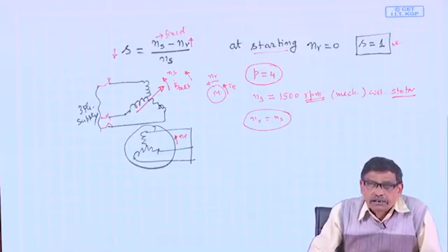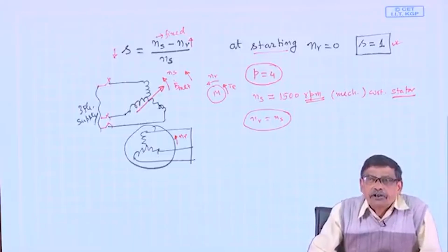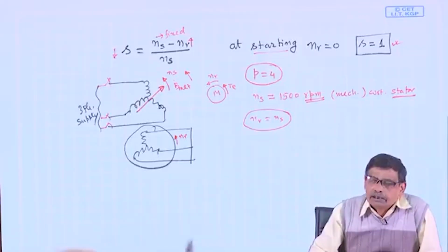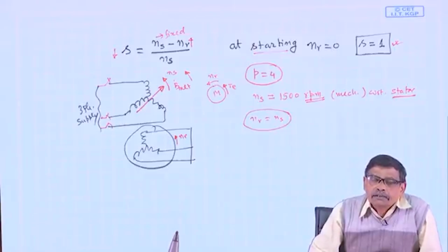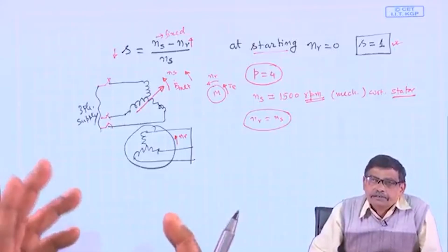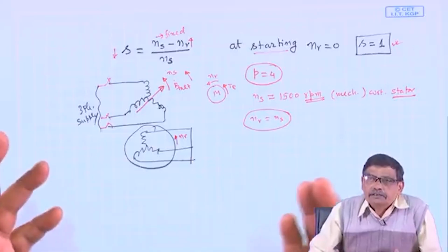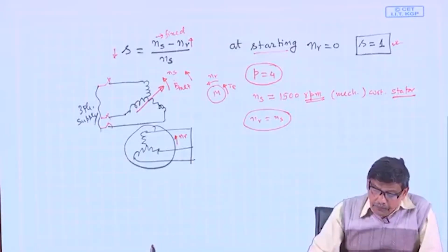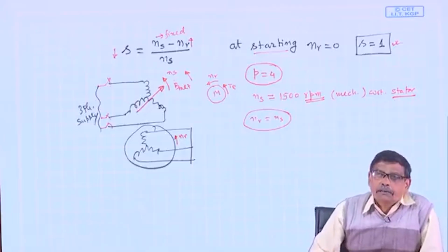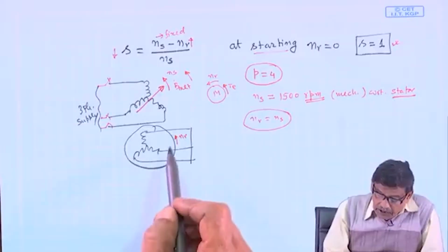Although the rotor circuit is closed, it is devoid of any induced voltage, therefore there cannot be any current, and there is no Br, no rotor field. Only Bs is present, which itself is B net at that time. Therefore, no torque will be developed and the rotor will run at Nr.